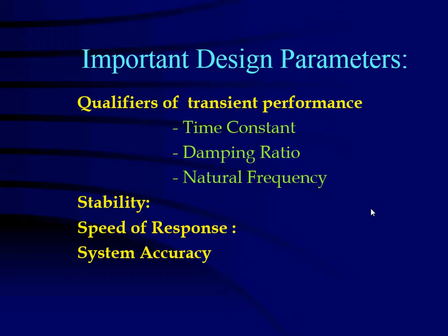And this is going to tell us where it is, what the position is. If you feed this back to the amplifier here, and you also have the setup in here, you compare the two, and this device is going to command the DC motor to either increase the torque or decrease it. Do you see how it works?